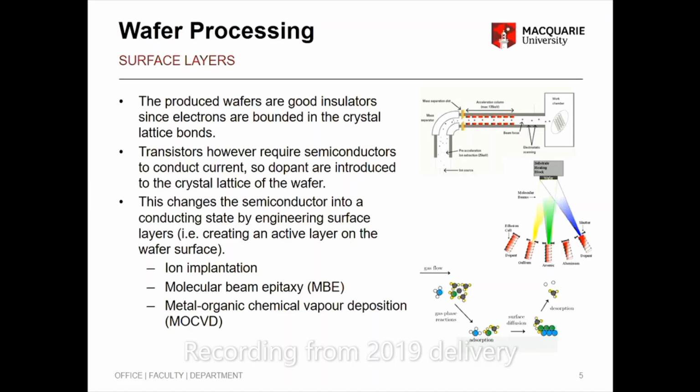So you actually have the wafer in here. This is done in the fab. They have to dope the wafer so that it has enough either electrons or enough holes so that it can carry current, right? So this is a controlled process. They have all the apparatus to make it more controlled and dope the GaAs wafer, or whatever the wafer is, enough so that it has a surface layer built on top of it.